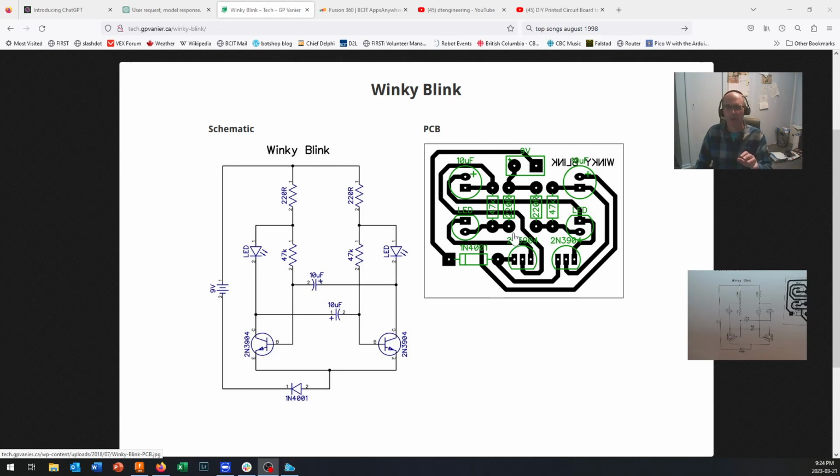We'll develop this drawing first, and then use the parts that we place in here to create this drawing second. What that lets us do is know that all of these traces are connected properly in accordance with the schematic diagram. Now, if you screw up the schematic diagram, your printed circuit board is 100% going to have the exact same errors that you put into your schematic diagram. So getting the schematic correct is a really important part of your design.